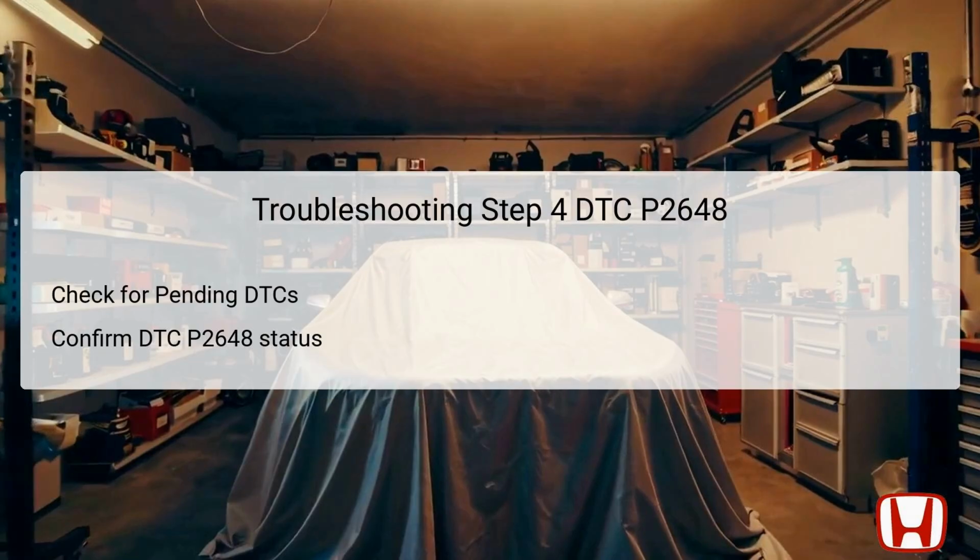The fourth troubleshooting step involves checking for any pending or confirmed DTCs using the HDS. At this stage, the technician needs to ascertain whether DTC P2648 continues to be indicated after performing the previous tests. If the code is confirmed, it indicates that the issue persists and further investigation is warranted.